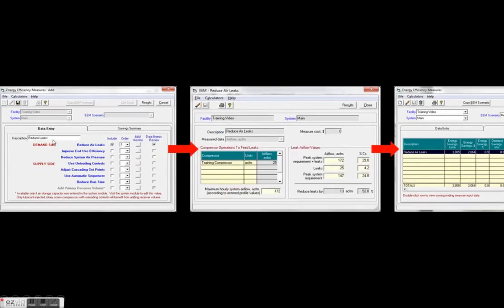Repair the leaks in the compressed air system by replacing the leaking fittings, valves, and other components. A regular check of the compressed air system components will detect leaks before they become severe enough to adversely impact electricity cost and/or cause mechanical problems. Leaks can account for approximately 20% or more of the compressor's flow output in an unmaintained system, and for a well-maintained system, leaks can account for 10% of the airflow. Repairing air leaks will reduce energy usage and costs associated with operating the air compressors.